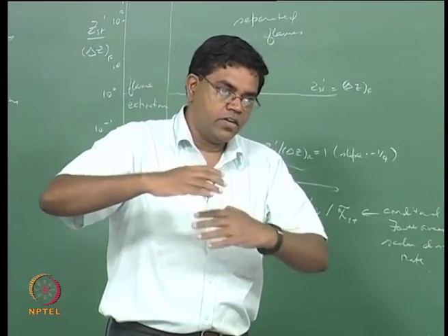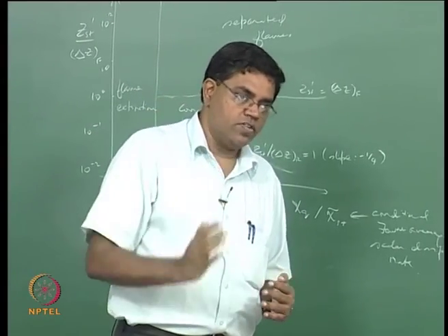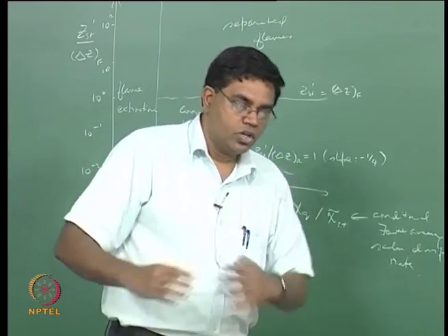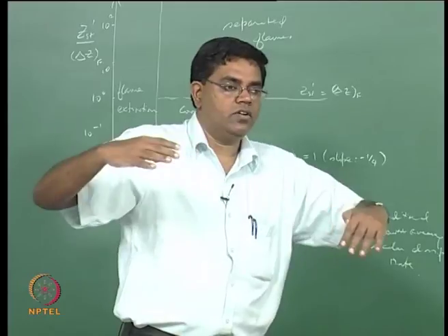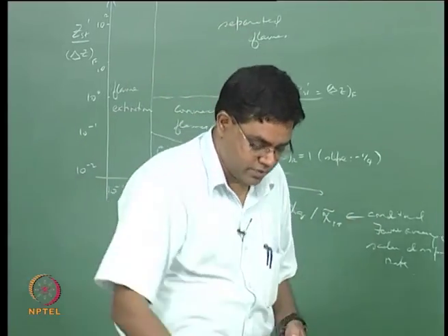So this begins to separate the flames, because the flames are effectively dictated by what's near the stoichiometric surface for the reaction zone, and if you have these things going on, you will create intermediate regions of stoichiometric surfaces, so the original flame is essentially broken.